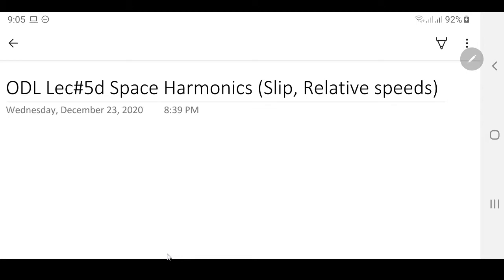This is the last lecture for the fifth part, in which we have been discussing the space harmonics. For those who have lost a little background knowledge, space harmonics were those harmonics produced because of the winding distribution, which means that the stator winding was distributed instead of concentrated. So a lot of harmonics were introduced, and the only theoretically possible way to make these harmonics disappear was to have distributed winding, so that the G value equals infinity, which means an infinite number of steps. We have seen a lot of space harmonics.